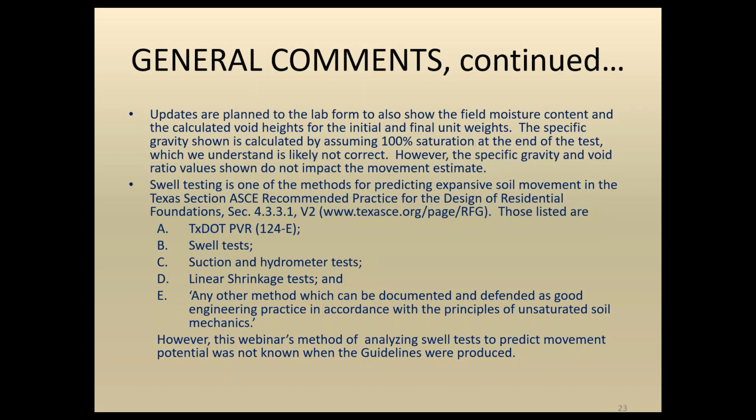So swell testing is one of the methods for predicting expansive soil movement in the Texas section of ASCE's recommended practice for the design of residential foundations. There you see a link to that publication. It's available for free.